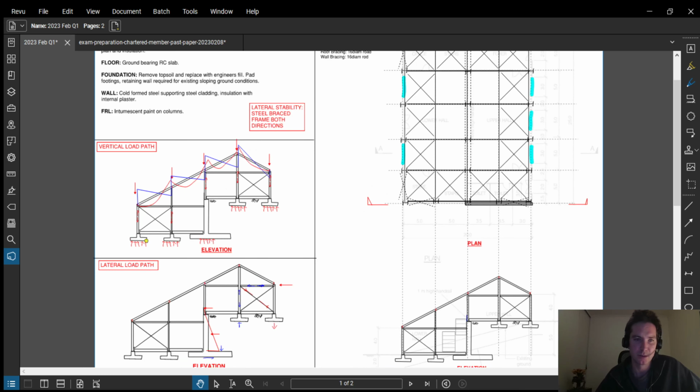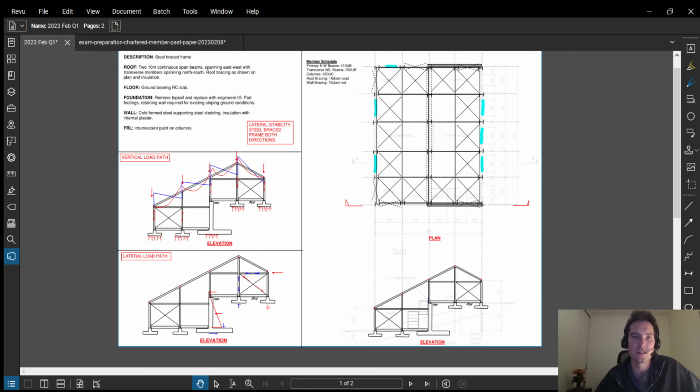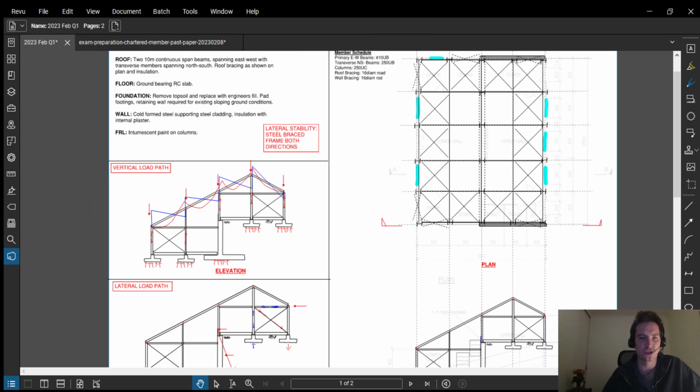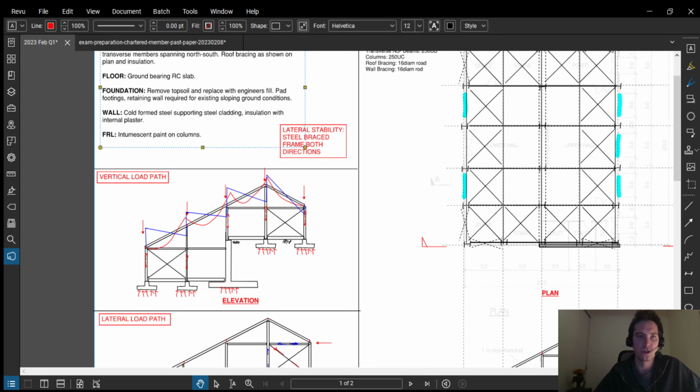Our shallow foundations mean I don't need to bring out a piling rig on site because my foundations are much shallower. And a fourth reason you might recommend scheme 1 over scheme 2 is the fact that the slab is actually bearing on the ground. Because we stripped off that top 300 of topsoil and replaced it with a superior fill, our slab is now bearing straight onto the ground as opposed to being suspended off piles. So we should be able to get away with a thinner slab.